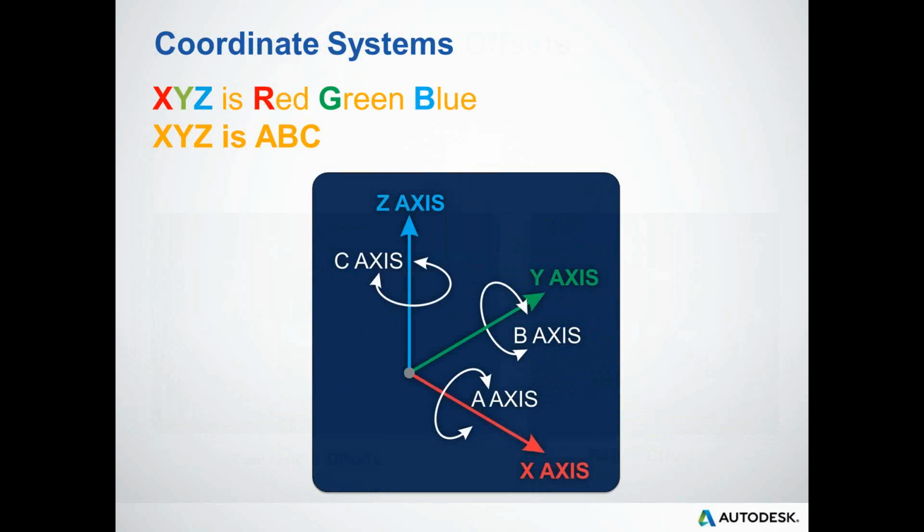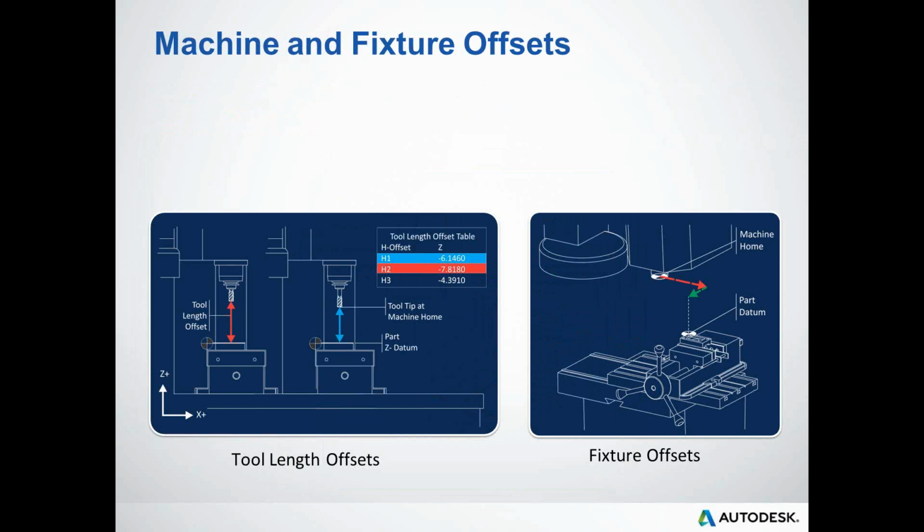When we program parts, we use basically standard or nominal size tools, a 1-inch end mill, 3/4-inch end mill. But when you're out in the machine and you're putting a micrometer on these things, it might be 0.990 instead of 1 inch, or it could be 0.365 instead of 0.375. That would be where the tool offset is used, and that's done at the machine control. The G-code simply throws a T switch or a D switch or an A switch to activate the right column from within the control offsets.